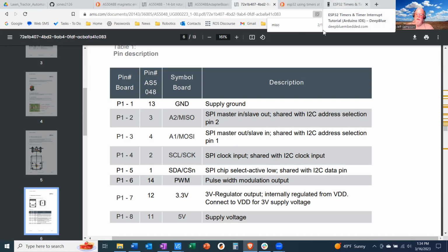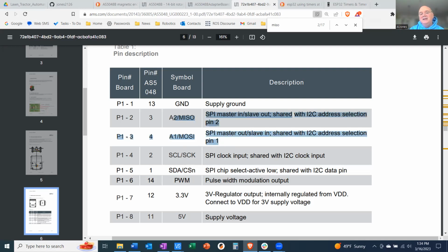Yeah, I was wondering if this could be an interrupt driven sensor effectively. Because right now it's an absolute position encoder. And so I've got it running at 20 hertz or so. And I'm wondering, could it be an interrupt based sensor?